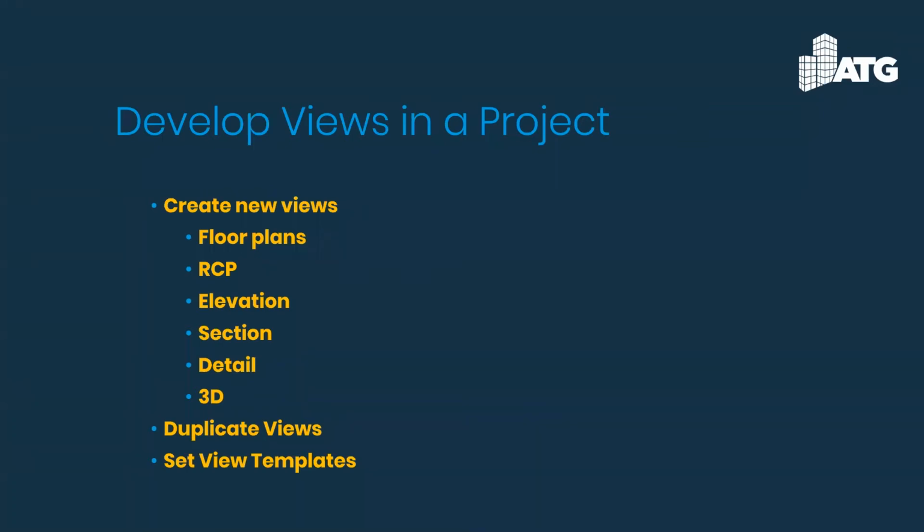So again, positives and negatives about either one. If you don't have the Express tools, I would probably say to pre-create those, create them up to the types of buildings that you develop, instead of building them up as you go, because it does take a bit of time to set up all of those types of views within a project.